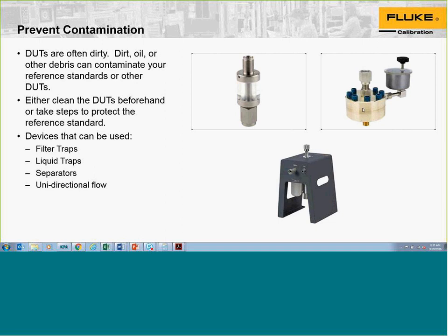of the media. They're useful in situations where you have, say, a hydraulic deadweight tester that works on oil, but you don't want to contaminate your device under test with oil. You want to keep it, say, with water. So use your oil deadweight tester on the bottom, fill the top up with water, and so now your device under test is seeing water, and your deadweight tester is being operated in oil. There are additional uncertainties or sources of error associated with these, but they're useful in many applications, especially for higher pressures.